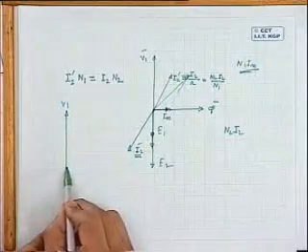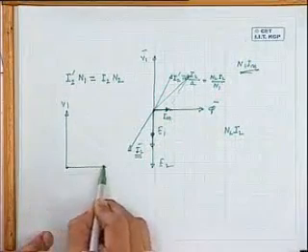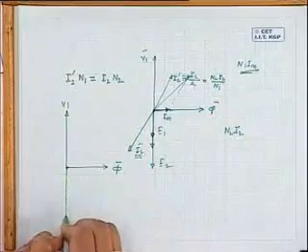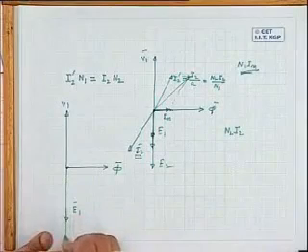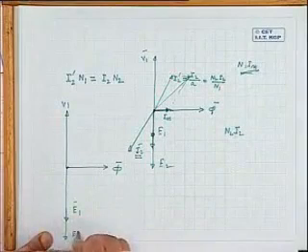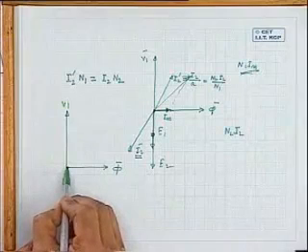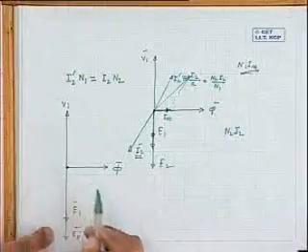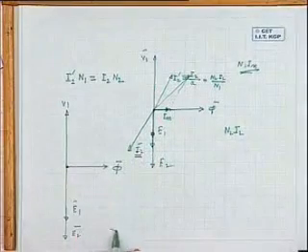Suppose now the transformer is ideal. Then in that case, what will happen? This is V1 voltage. IM is now vanishingly small, 0. Phi is there. This is the flux phasor. Your induced voltage phasor will be E1 and E2 will be there. Primary current drawn from the supply is now 0 because of this idealistic situation. IM I have assumed 0.